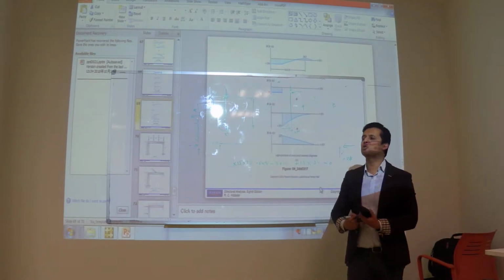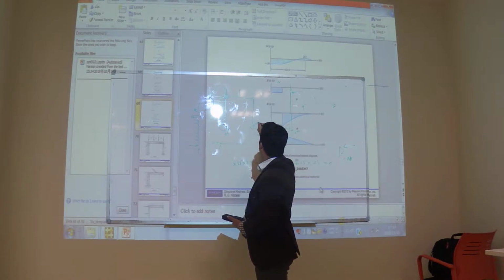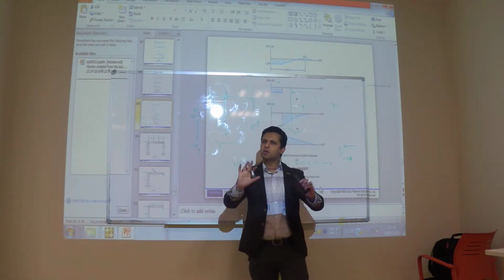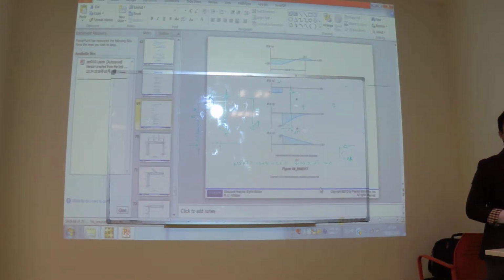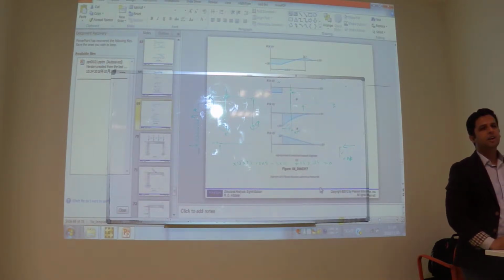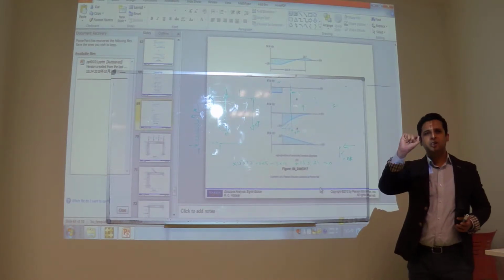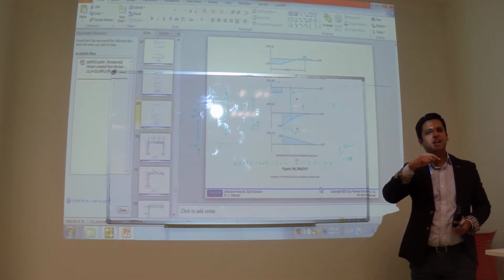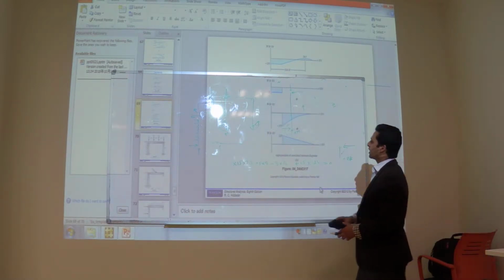If a frame has two fixed supports, one fixed support here, another there, it will become indeterminate. You cannot solve this frame now. Do you understand? Two fix we cannot solve, but just one fix we can solve it. You have to apply the equations for determinacy and indeterminacy. Okay? You have to check.